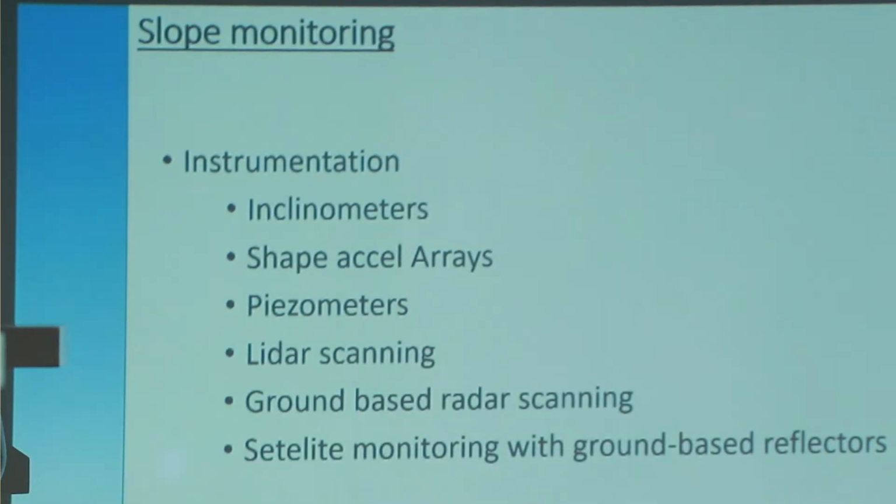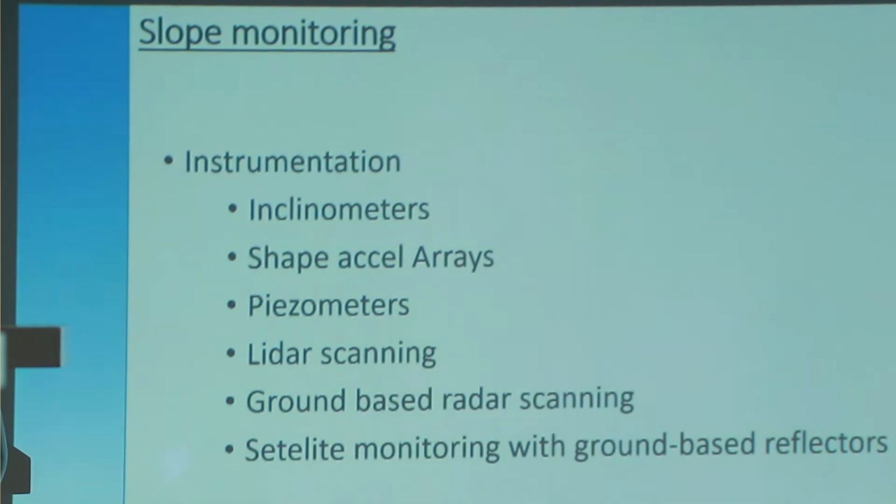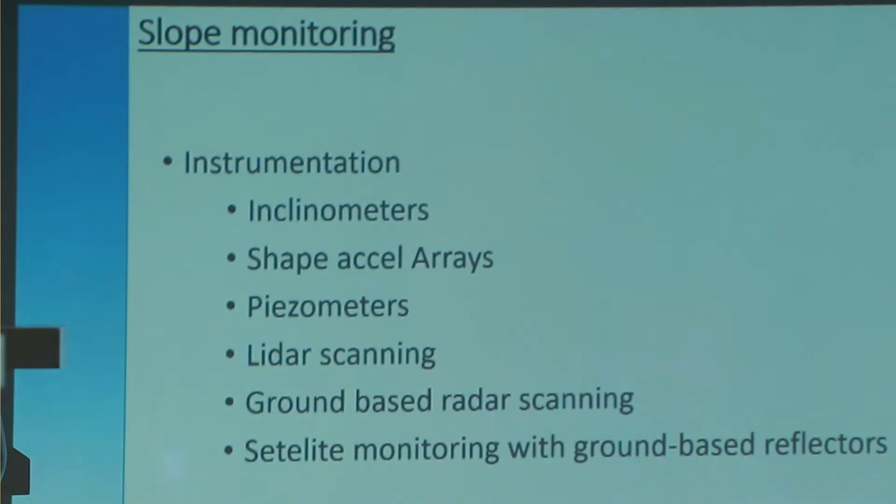The instrumentation we use in the monitoring of slopes includes inclinometers to measure the deflection, and one new thing, shape accelerometer arrays, which I used. It's a three-dimensional array.